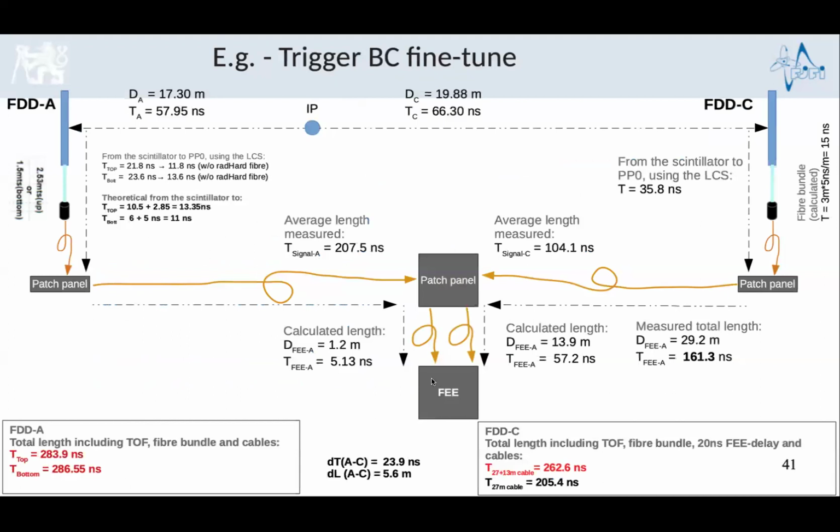There are different levels. In the front end electronics, you can already implement some conditions or some trigger logic. For example, in this detector, one can put an OR condition when there is a signal in one of the two modules, or an AND, a coincident signal from the two modules.